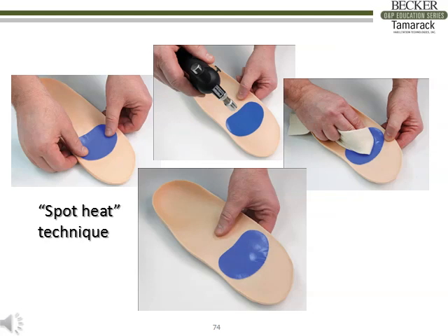If you use a heat gun, a small concentrator helps. It is possible to scorch the PTFE film, and the film and fabric components may delaminate if heated too long without being supported. As you heat the PTFE film, it will have a slack look when ready. It does not turn clear or give you other indications of when it is heated sufficiently.